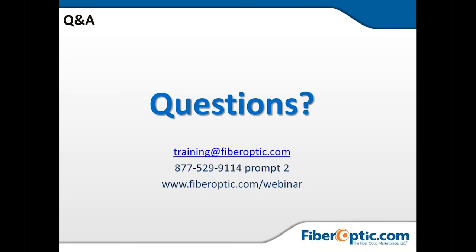And this is very typically done at the amplifiers. Depending on your loss and depending on your bandwidth, you may have to compensate in between. But generally I would expect to let it disperse and then compensate, because the pre-compensation is just going to give us some of the same issues that overcompensation would give us if we did that at the beginning.